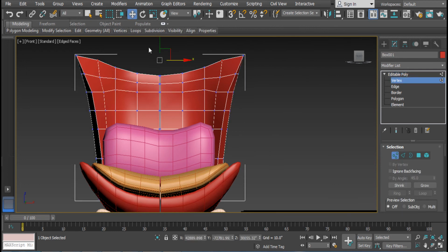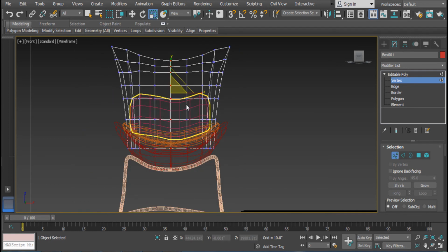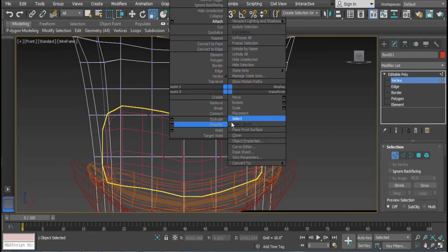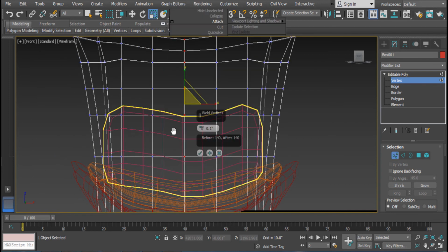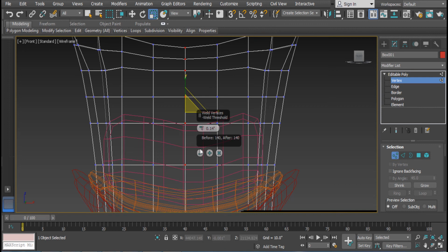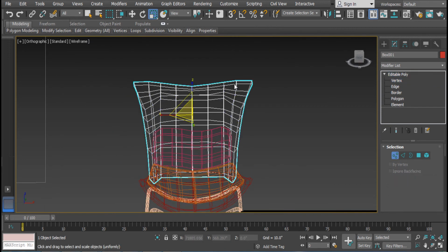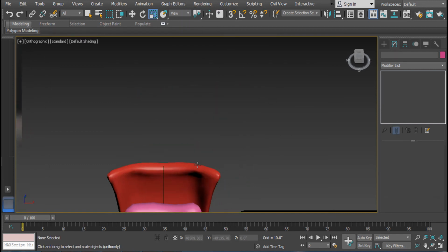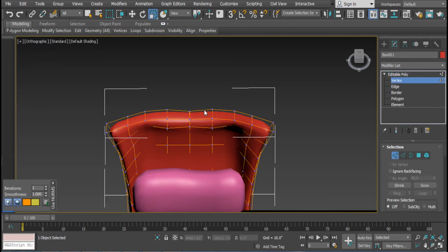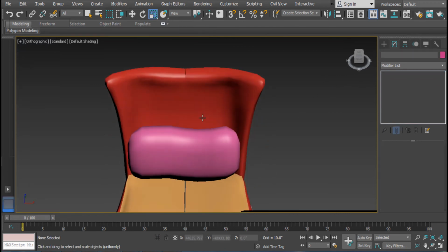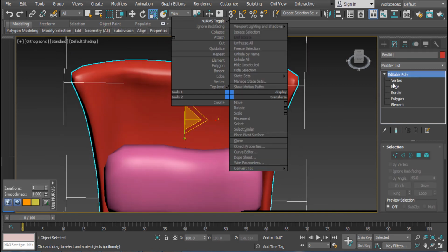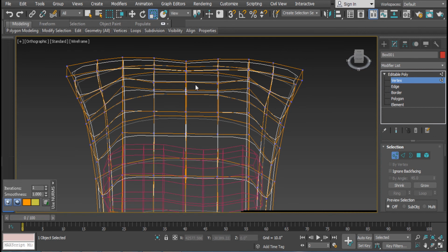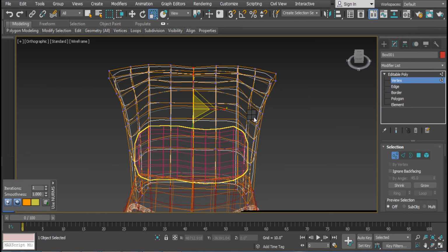So the remaining part is attaching those two objects in mirror. While attaching, just copy it. And one more thing, you need to make the pivot the center of the object, almost the middle of that object. Once you weld the in-between vertices, you need to be very careful. Also, check the option box. Sometimes you need more values to weld.